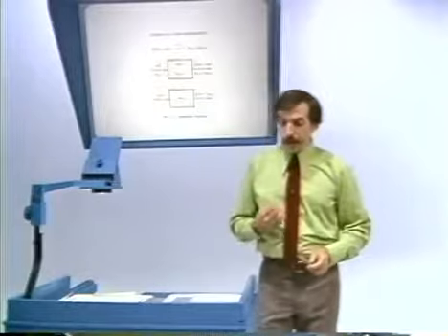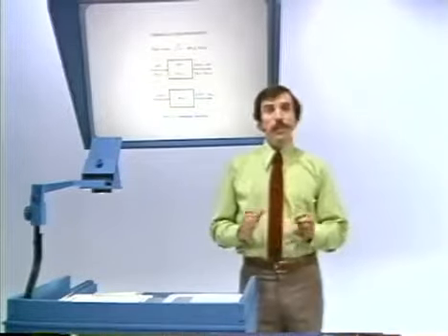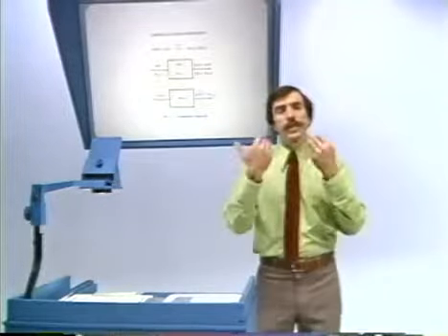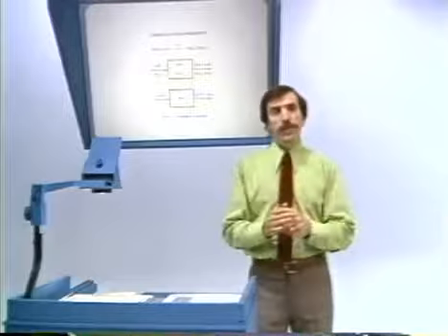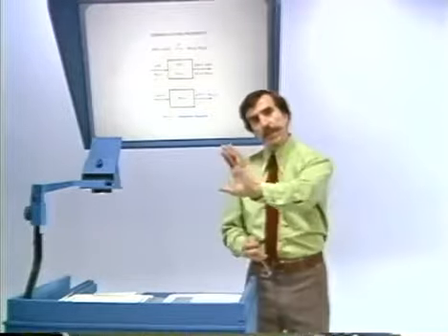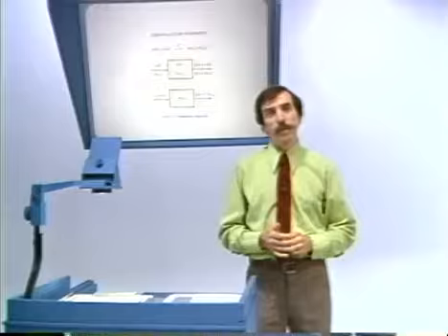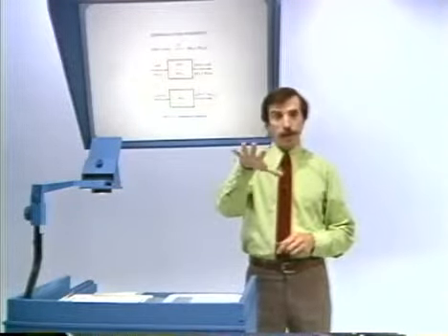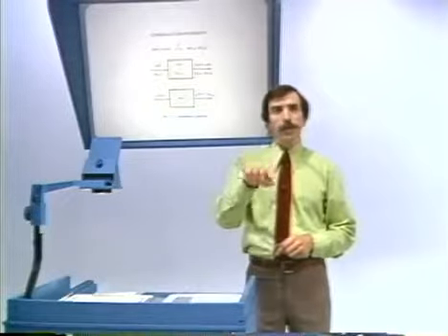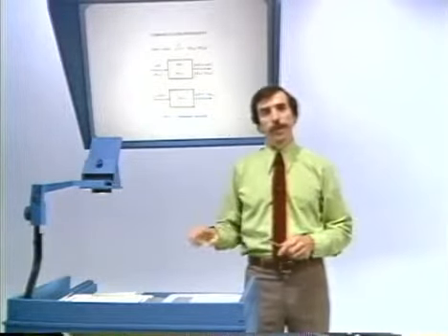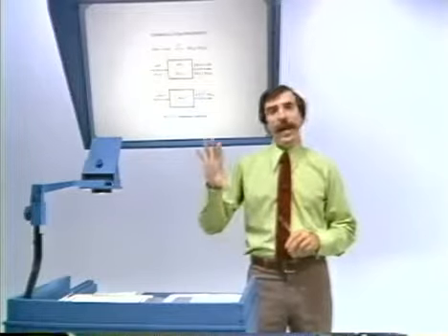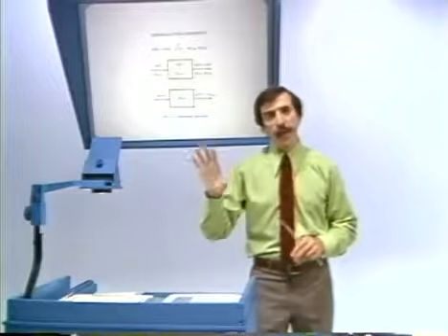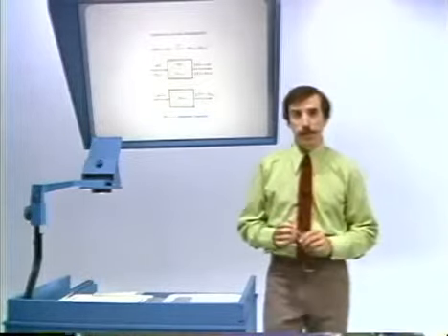So, in fact, the convolution property simply tells us that in terms of a decomposition of the signal in terms of complex exponentials, as we push that signal through a linear time invariant system, we're multiplying by the frequency response the amplitudes of the exponential components used to build the input, and that sum, in turn, is the decomposition of the output in terms of complex exponentials.